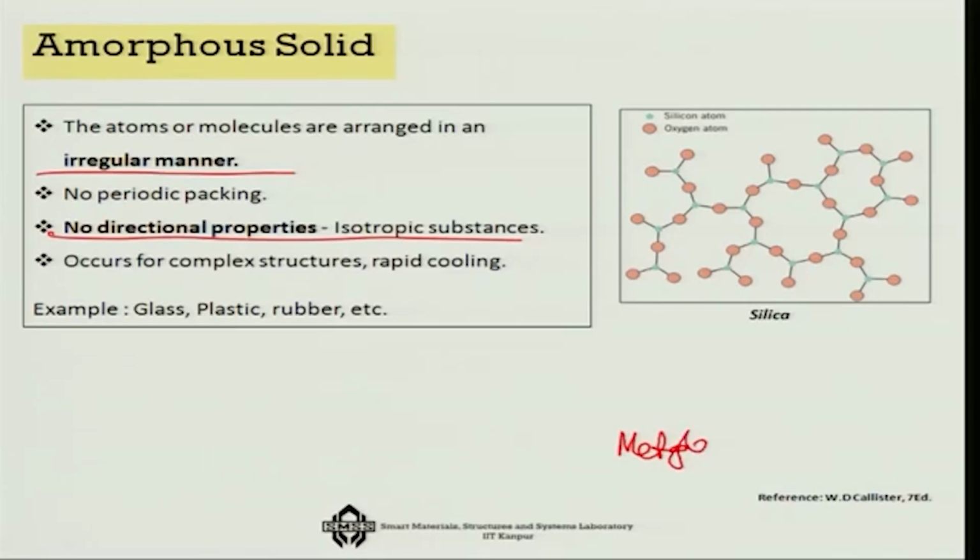I will talk about different types of metallic glasses, something like BMG, bulk metallic glasses. They are becoming very important in today's context. So, this is one way. By controlling the cooling rate, if the cooling rate is very slow, you get a crystalline structure, but if you make the cooling rate very fast, then you get the glassy structure out of it. So, that is one way of generating this amorphous structure.